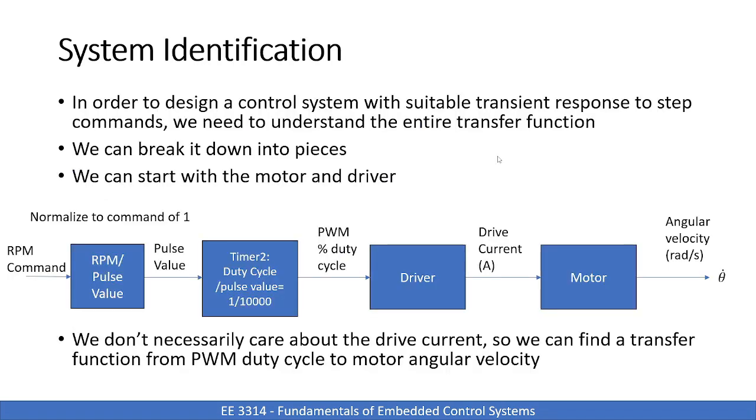Okay, system identification. This is a topic that's pretty popular with systems. MATLAB has a lot of tools for coming up with the model for a particular system, but a lot of times you want to come up with a mathematical description of a physical system. That's important so you can simulate it. You can use that model to combine with your controller transfer function to get an overall closed loop transfer function, and that is what you're going to look at the performance of.